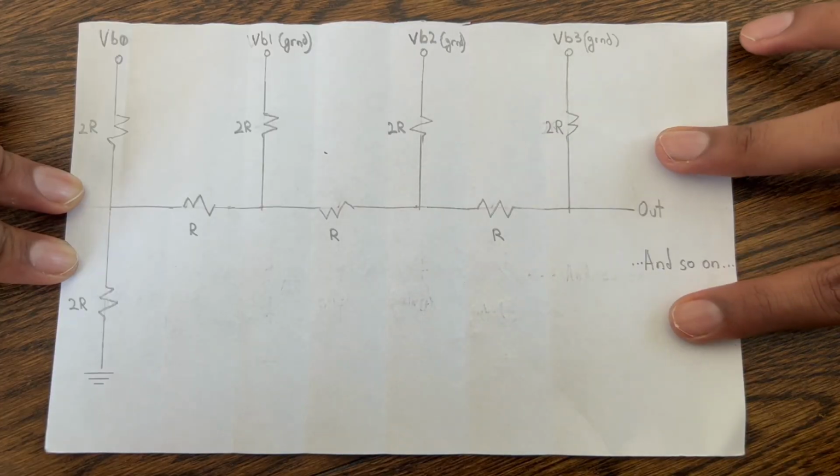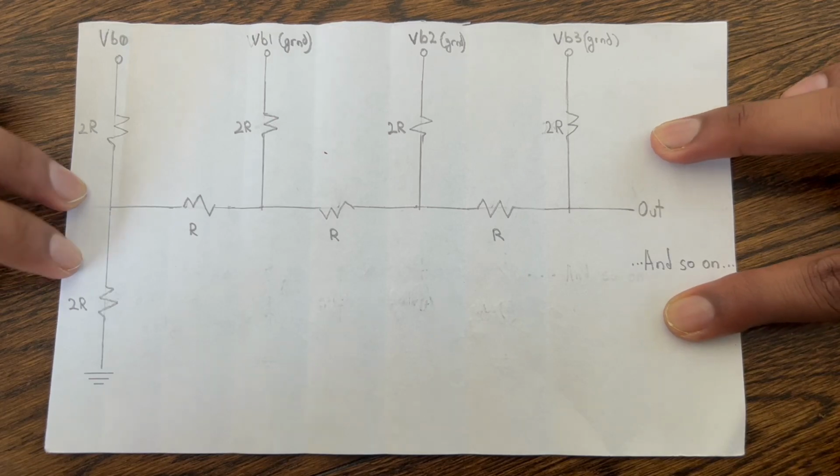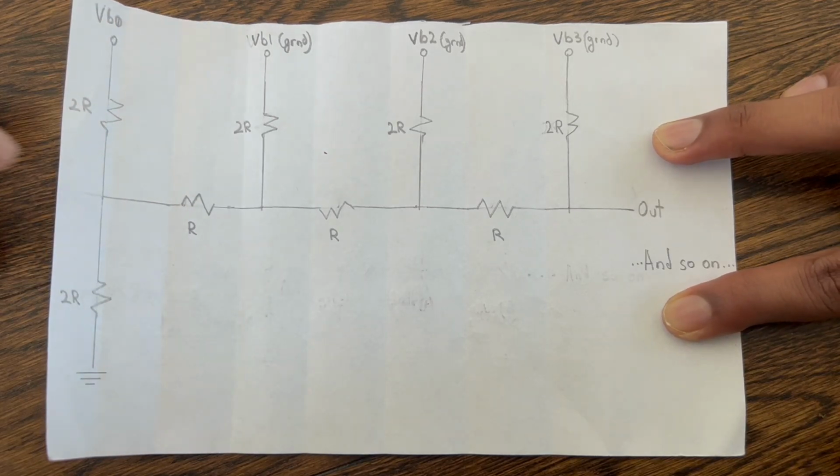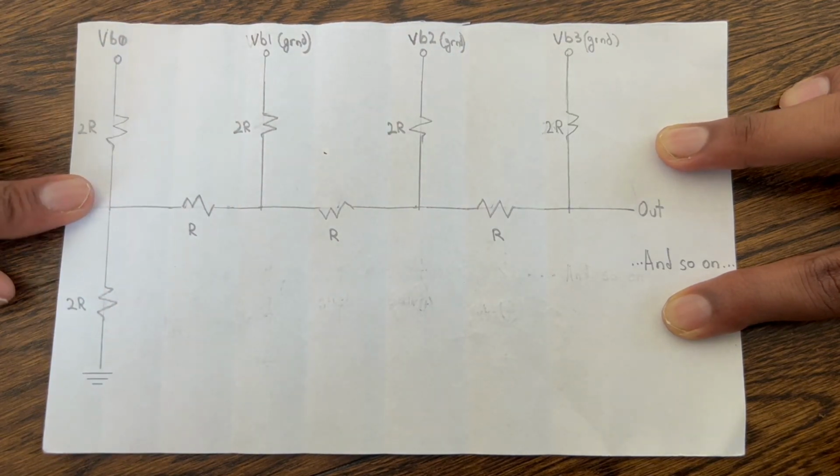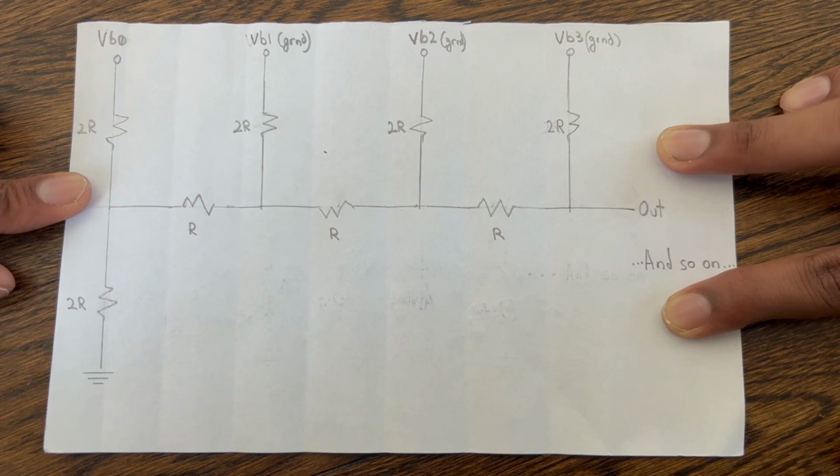We can also find the voltage levels of each bit using the idea of superposition. In order to do this, we should have one slide switch on and turn the others off. And we have to do this for each of the varying voltage sources. For us, 4 times. And then sum all those results, which is how superposition works. We will also use Thevenin's equivalent circuits to calculate things.